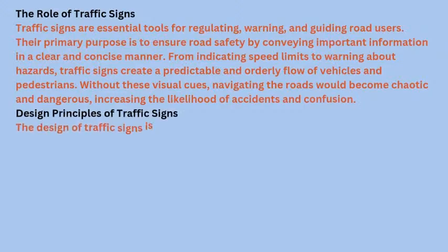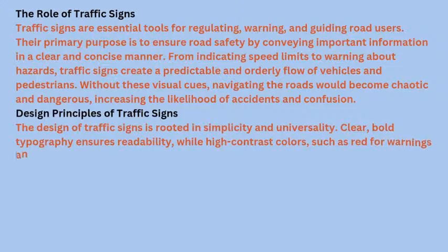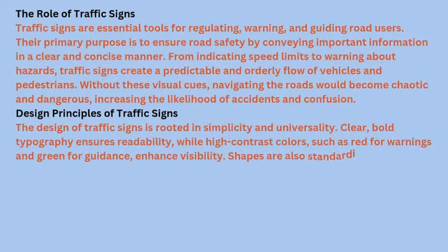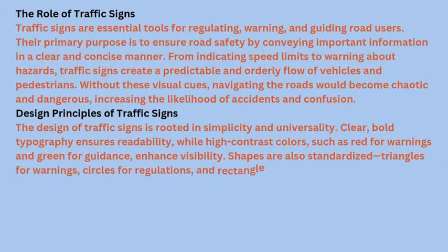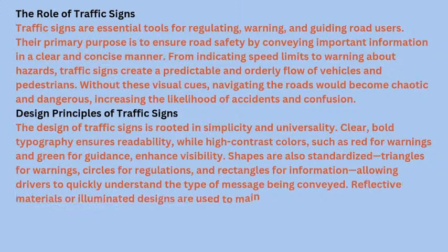Design principles of traffic signs. The design of traffic signs is rooted in simplicity and universality. Clear, bold typography ensures readability, while high-contrast colors, such as red for warnings and green for guidance, enhance visibility. Shapes are also standardized: triangles for warnings, circles for regulations, and rectangles for information, allowing drivers to quickly understand the type of message being conveyed.